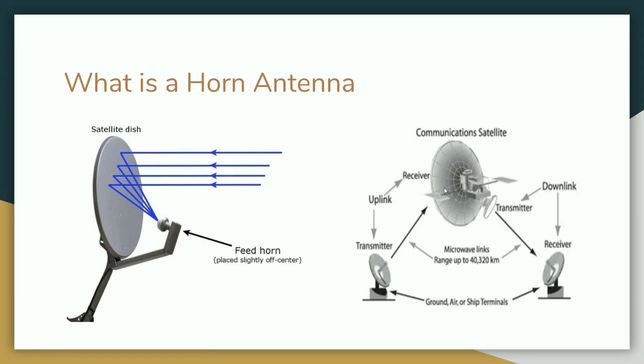Horn antennas are commonly used as the active element in a dish antenna. The horn antenna is pointed towards the center of the dish reflector. The use of the horn rather than a dipole antenna or any other type of antenna at the focal point of the dish minimizes loss of energy around the edges of the dish reflector. It also minimizes the response of the antenna to unwanted signals not in the favored direction of the dish.